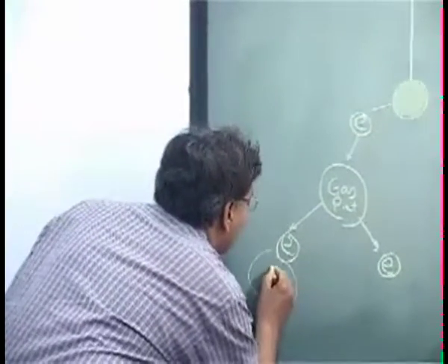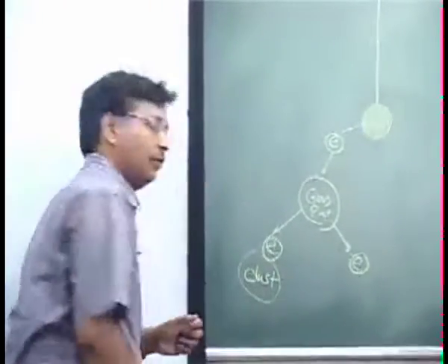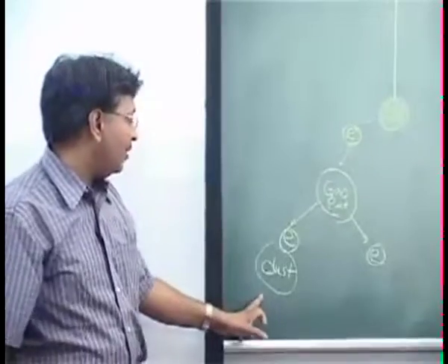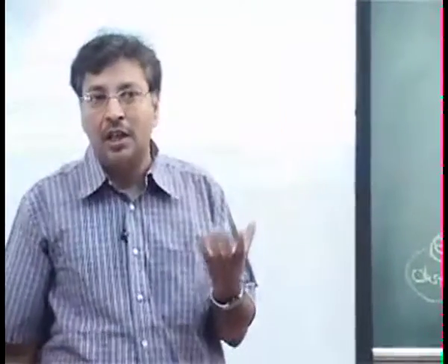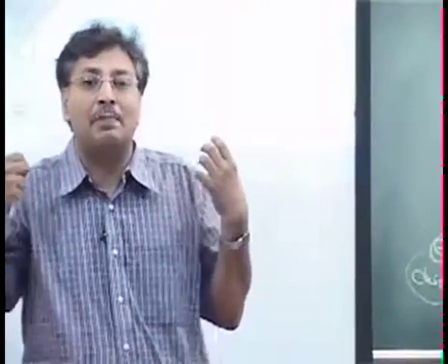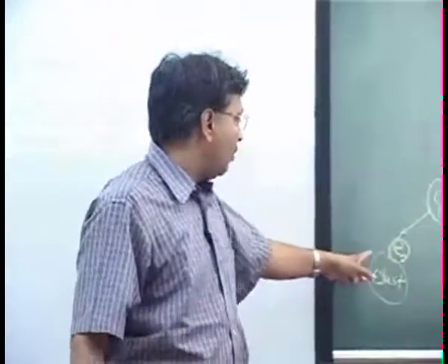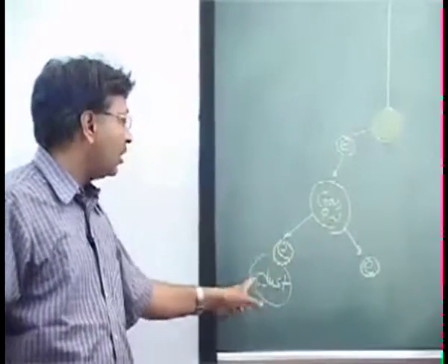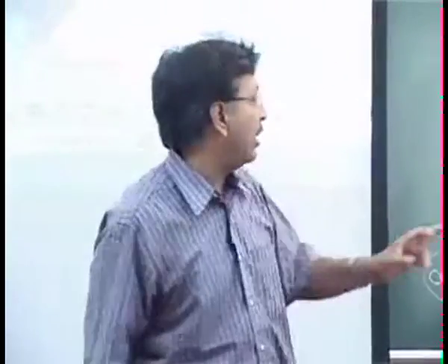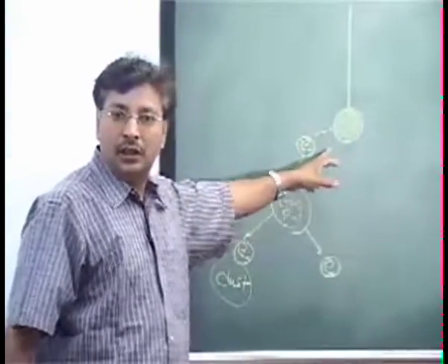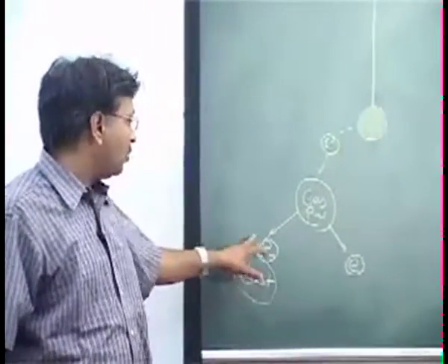Okay, so these electrons can sit onto the dust which you want to remove. So in the process, what happened? The dust particles have become charged because the electrons are piggybacking onto them, just sitting on the back of them. Once they are there, the dust particles will also start traveling in the direction opposite to the discharge electrode and go towards the plate, because they were going towards the plate anyway.